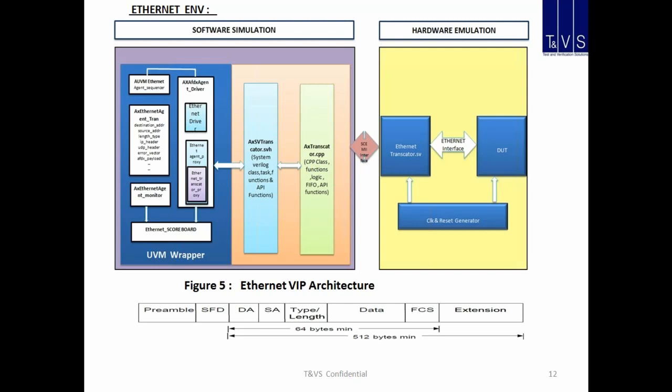So what we experienced is that if it is possible and if it is not too complex to put some of your checkers in the hardware, that would really be beneficial from performance, because let's say your response is coming from your DUT, and over there itself, if you can check the scoreboard, then you will not have to pass all that data to the software side.